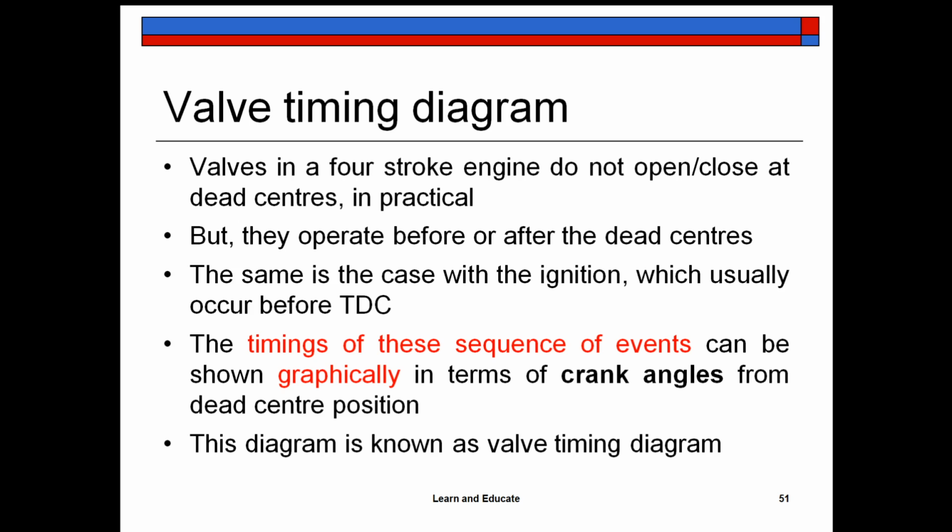So valves in a 4-stroke engine do not open or close at dead centers in practice. Theoretically, we say that the intake valve will open when the piston reaches the top dead center, right? Theoretically, but actually that's not the case. Just before the piston reaches the top dead center, the valve will open. Similarly, the exhaust valve. They operate before or after the dead centers. The same is the case with the ignition also.